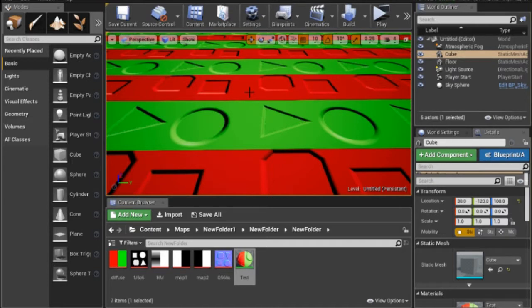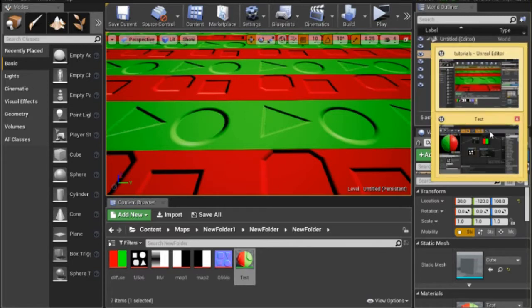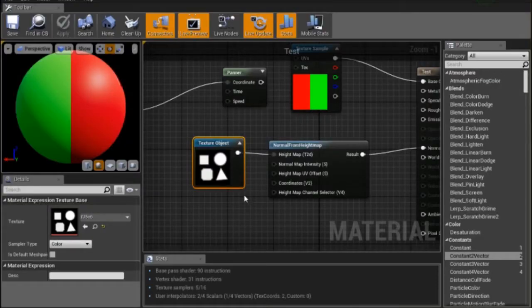So now, if you want to change it from going deep to going high, you have to go into the 2D software and invert the colors so you can change that. Another advantage of using height maps instead of normal maps, besides that it's easier to create them on your own, is that you can set the normal map intensity.